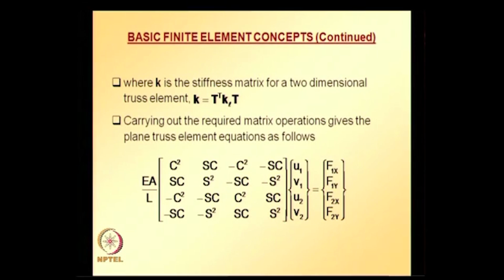And the nodal displacements for any 2-dimensional truss can be computed using this equation. Once nodal displacements are known, the axial forces, stresses, strains in the elements can be computed by first calculating the local element deformations, that is, here when we solve this equation we get u1 v1 u2 v2.